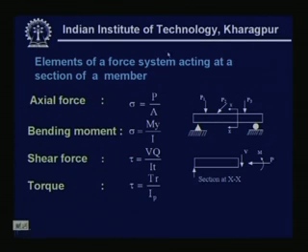Please note that T is the thickness, what we consider there as B, also the width of the section. Same thing here, it has been written as T. Although this particular beam is acted upon by loads P1, P2, P3 etc. and does not have any torsion acting on it, we have still written the equation for the torque, which gives the shear stress as Tr by Ip.